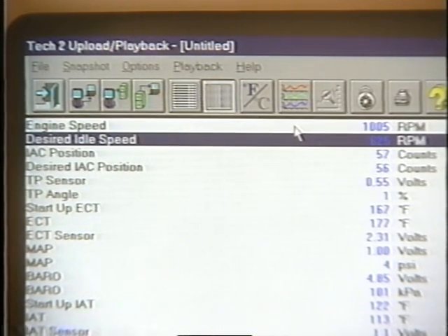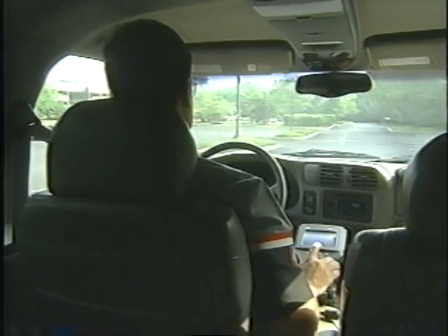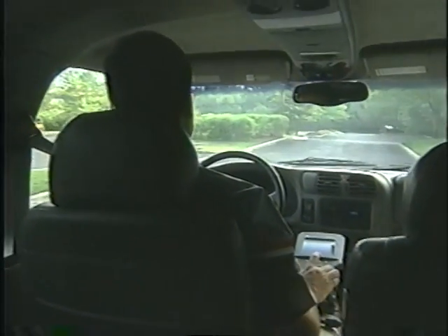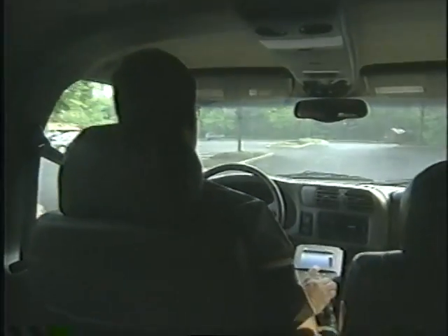An illustration in the reference guide explains what they can do. What you want to do now is plot 3 inputs on a graph, so you click on the icon for Display Graph. Based on your experience of the symptom during the test drive and on similar cases in the past, you suspect the mass airflow sensor circuit.